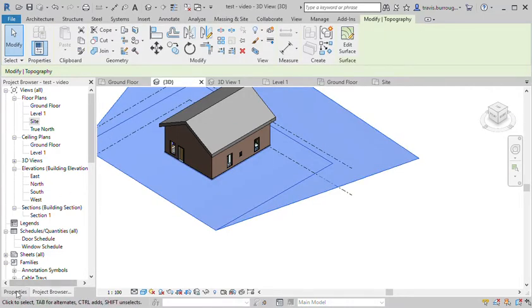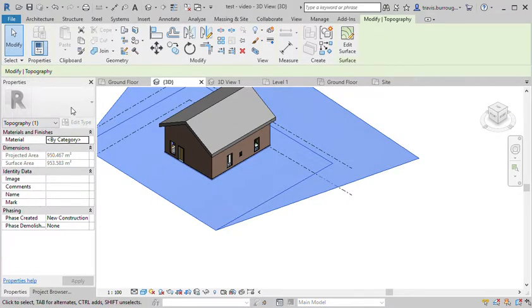Now you should be able to go back to the properties of that surface and change the material. Same way that we changed that height before, we can go to Material, click on these three little dots, and it's going to bring up a library of different materials we can use. So it's just kind of an appearance thing. So we've got, I'm just looking for grass or something that would look like outside. So plantage, foliage, that's going to look pretty grassy.